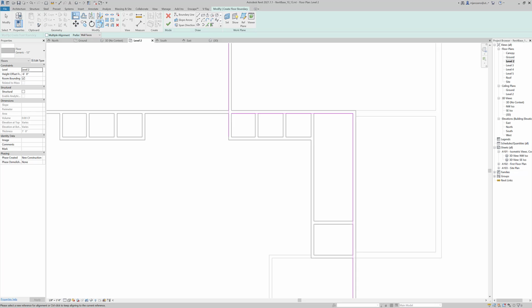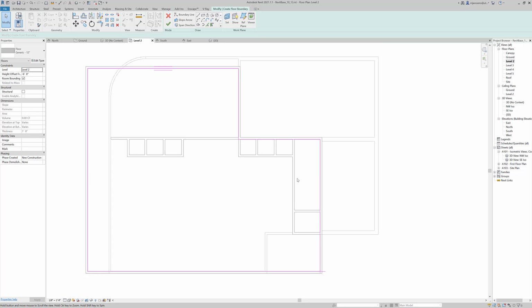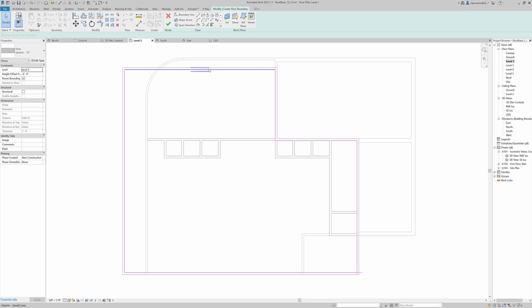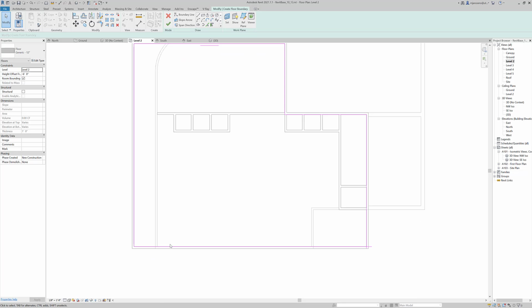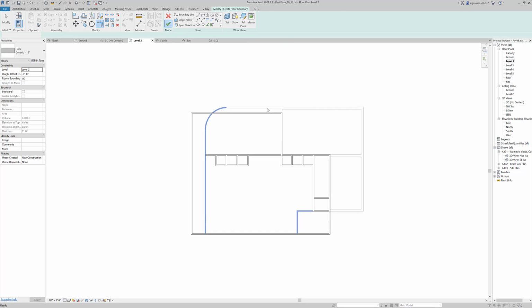So I am making the option to put the floors on the inside of the wall, and it's much more complicated than this in real life, because you'll have walls that are made of many different layers, and some layers the floor will go into, and then you'll have what's called a thermal break, so that the floors don't leak heat out into the environment. But for right now, let's go ahead and just put the floors on the inside, and if you want to expose them for some reason, you can push them on the outside if you have a temperate climate, for instance.